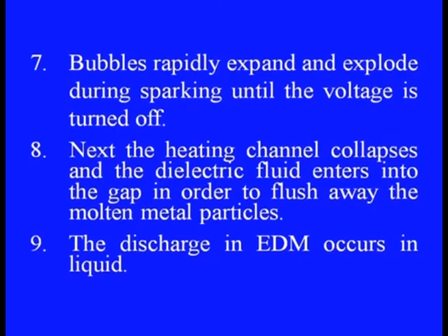Next, the heating channel collapses and the dielectric fluid enters into the gap in order to flush away the molten metal particles, which are also called debris. The discharge in EDM occurs in the liquid. The single spark theory is inadequate to explain the discharge.